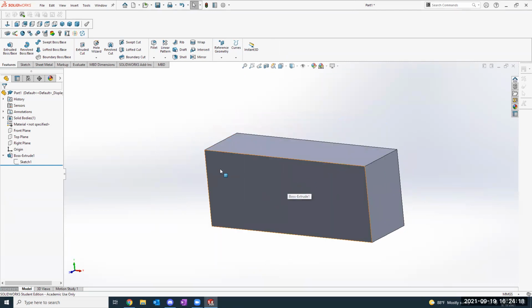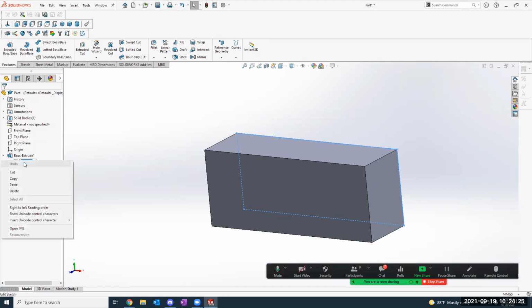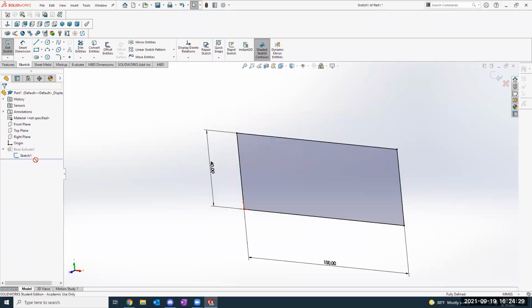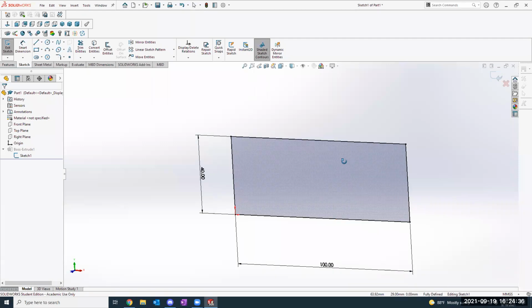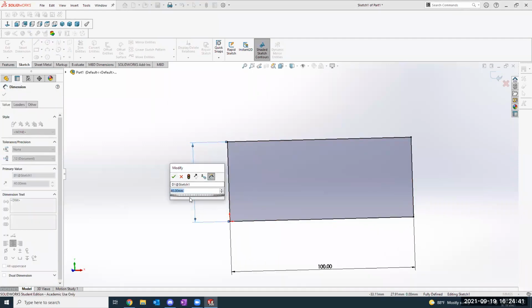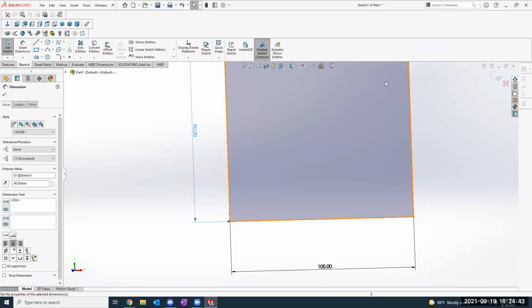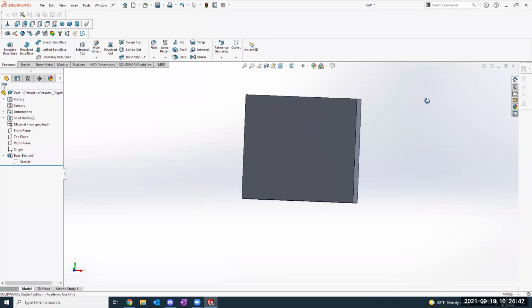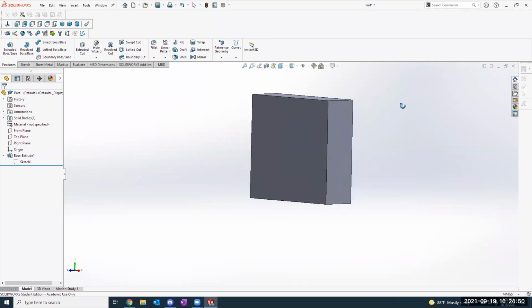What happens if you change the sketch now? All right, so we got a question from chat that I'm just going to go ahead and show everybody right now. What happens if you change the sketch now? Is it going to impact the body? So let's say we take this 40 millimeters and change it to 90 millimeters. And then we back out. And there's our block, which is now 90 millimeters tall instead of 100 millimeters tall.